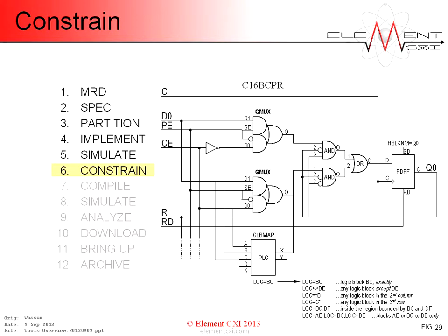For example, the asynchronous reset net can be marked as non-critical. Signals can be marked as external, which means they remain visible for simulation observation, and a high fan-out net like parallel load enable can be forcibly assigned to a long line resource.